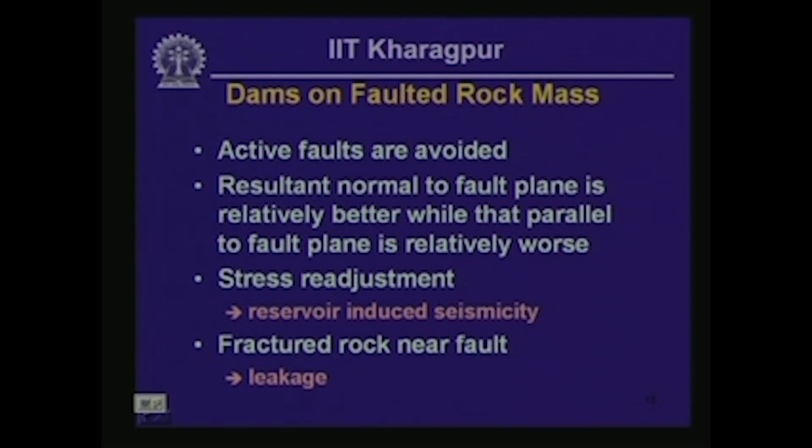You also need to consider while siting a dam in faulted terrain that fractured rock near a fault could provide pathways to water seepage, and this in fact has led to dam failures in the past. We are going to discuss this in detail a little bit later on.